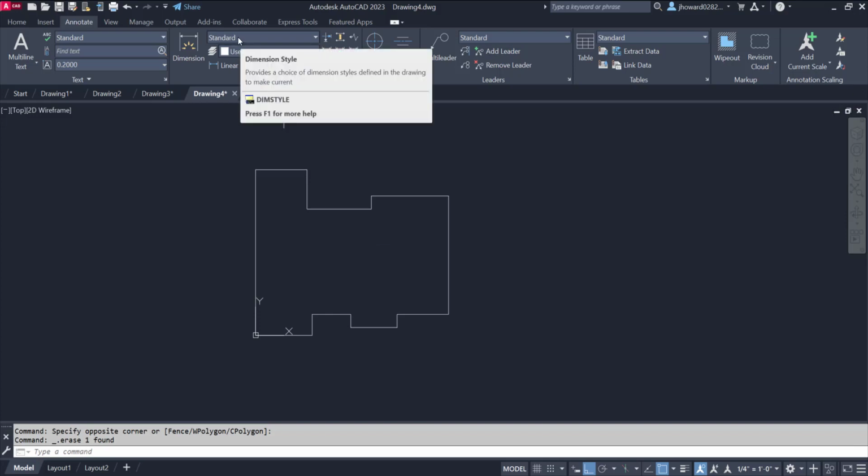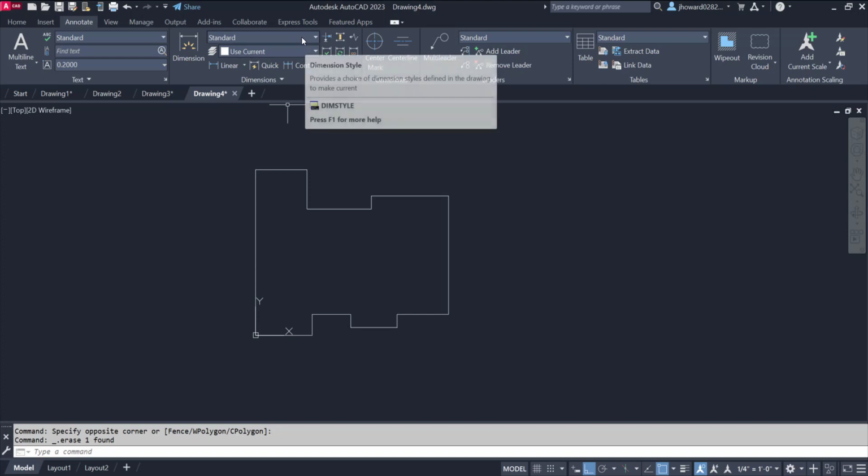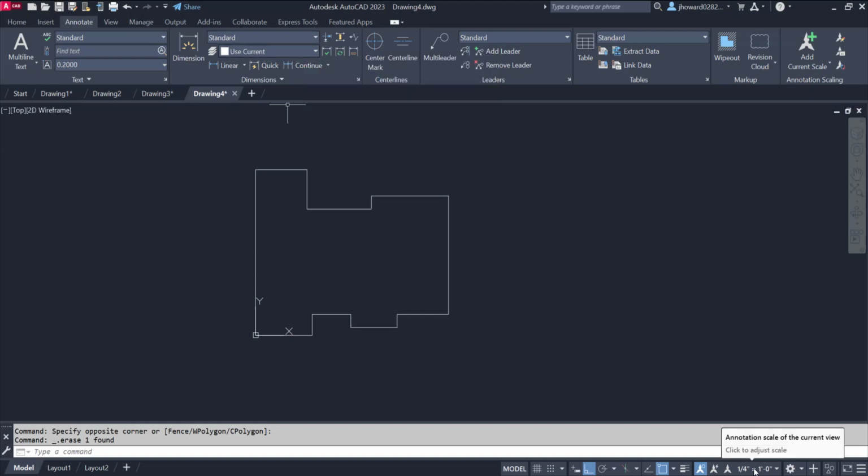This is where I would have to calculate it up myself to be able to give it a scale factor that would make my text look like 1/8 of an inch on my paper compared to a 22-foot line like right down here.